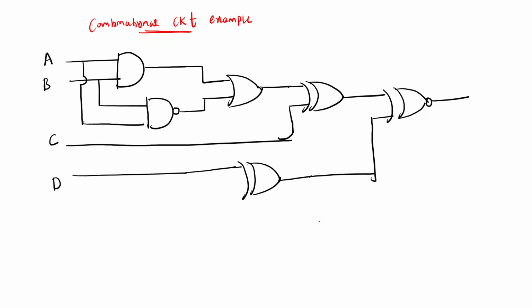I know that this is nothing but AB, and this is AB bar. This is an AND gate; by seeing this I can understand that this is a NAND gate. Let us consider AB equal to X, so AB bar equals X bar. Here this is an OR gate, X plus X bar, and that is equal to 1.